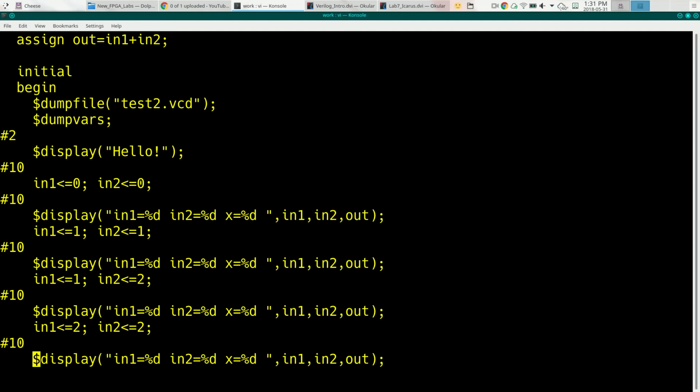And in the way that this is described in the handout, these are actually broken into separate pieces. There's one file that describes the circuit you want to test, and then a totally separate file that's actually the test bench itself. And the test bench just includes your circuit inside it. And then you're really just writing a bunch of input vectors and ways to look at the output.